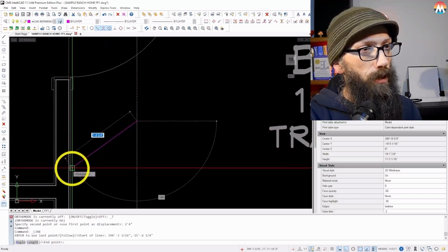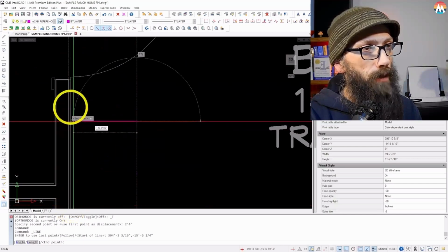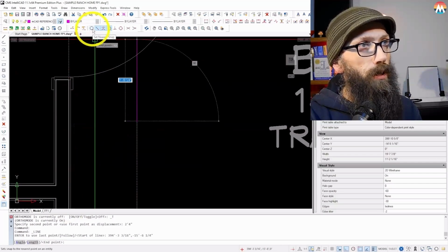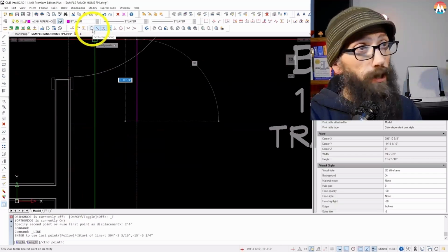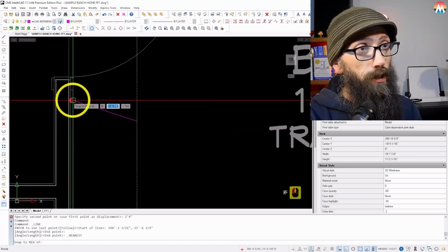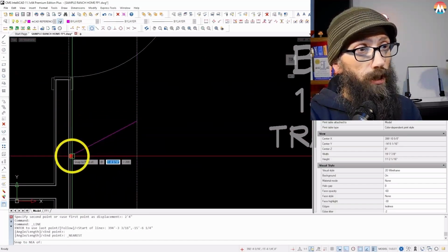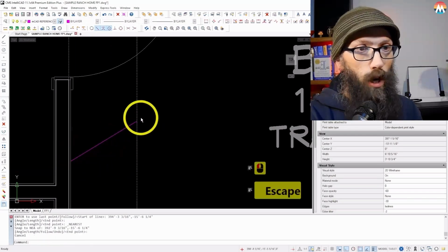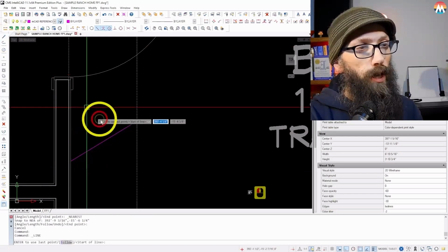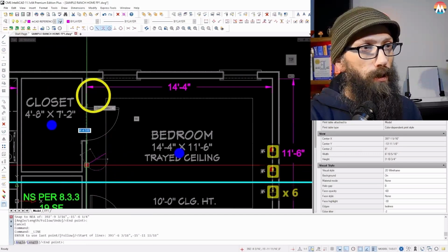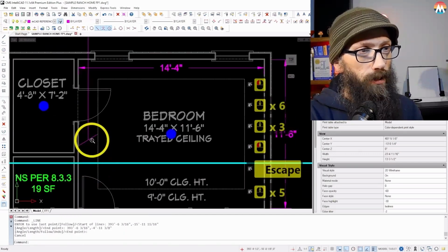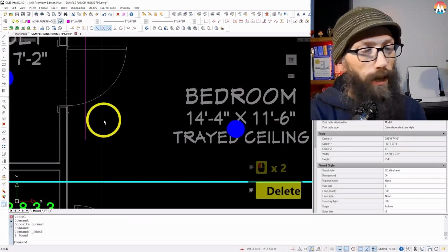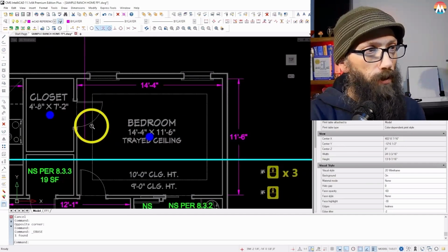But let me show you, if there wasn't one, I could go up here and select the nearest snap, and then anywhere on this sheetrock I could click, and it really doesn't matter where. I'm going to click right here. We just need a line crossing these two. And now when I create another line and snap to the midpoint, I am exactly at the halfway point of the wall and the edge of this outer ring of this tray.